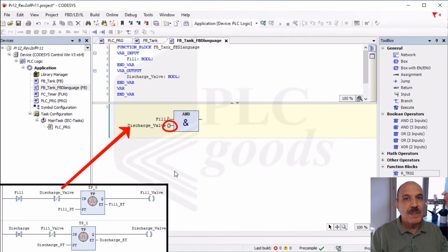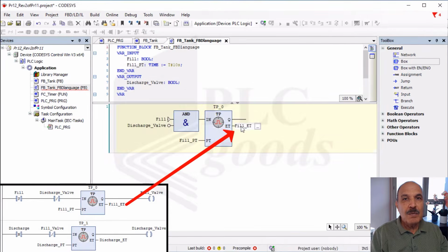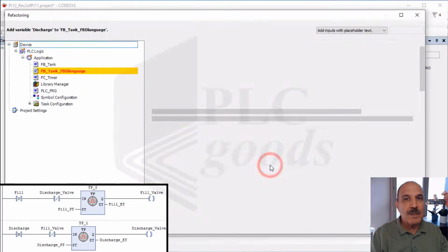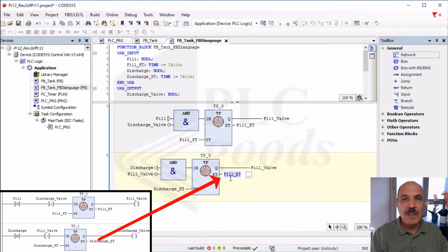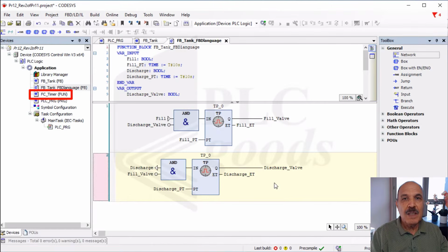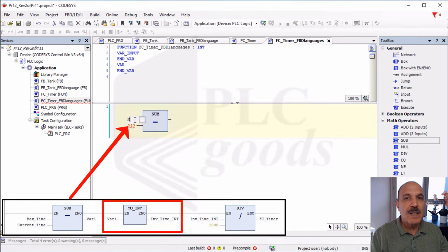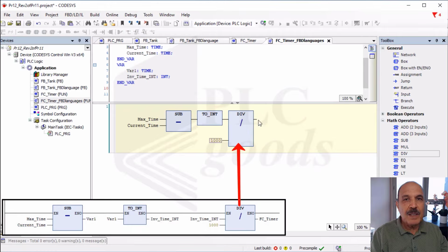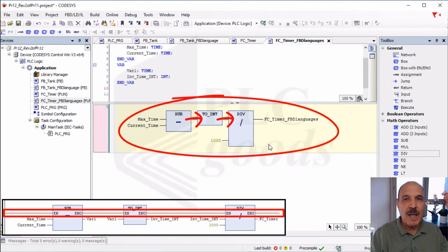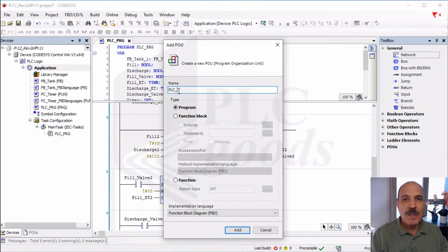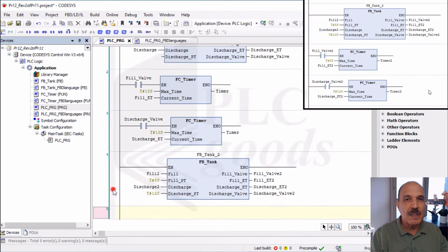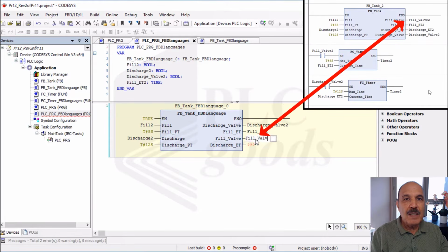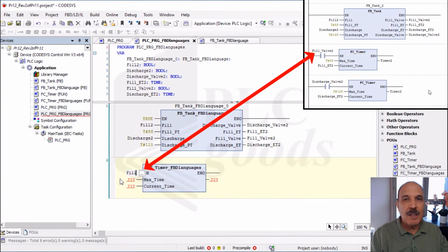The focus shifts from ladder logic to function block diagram language. The previously showcased water tank control project is rewritten in FBD, highlighting the language's similarities with the ladder diagrams. Function blocks are created integrating elements like AND logic and pulse timers, showcasing the language utility. The conversion extends to functions maintaining similarity across the languages.